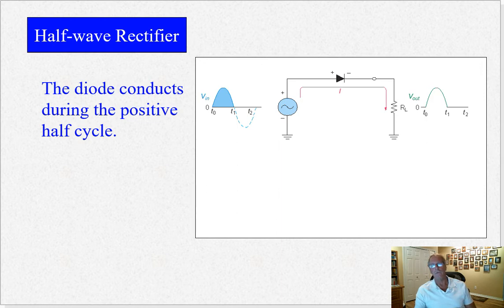This chapter is split into two parts. I should have mentioned that during the first one, but you'll see that that's how it was split up in the slides here anyway. So a half-wave rectifier is basically one diode that is inserted into a power supply circuit. We have AC current right here, and it's passed through the diode and then through a load, this load resistor. Now, current only passes in one direction, as you know, in a diode.